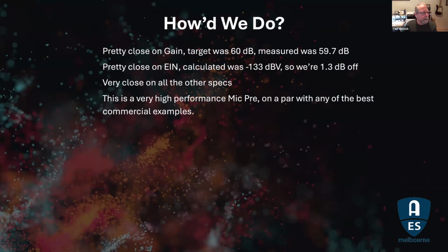So you're asking about PSR. So they're all going to be pretty similar. Most of these kind of parts are going to be... he's asking power supply rejection ratio. And that one I'm going to call as being in the avoidable noise area. But I'll say that the op amps that you typically find are going to have a PSRR in the say 80 dB kind of range.